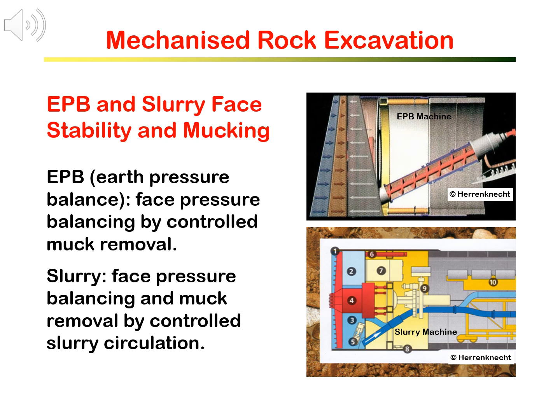In slurry mode, as in the lower figure, slurry pressure in the chamber is regulated by the slurry coming in and then leaving the chamber through the pipes. At the same time, muck is removed together with the slurry leaving the chamber. Chamber slurry pressure can be further regulated by the air bubbles marked as 2.